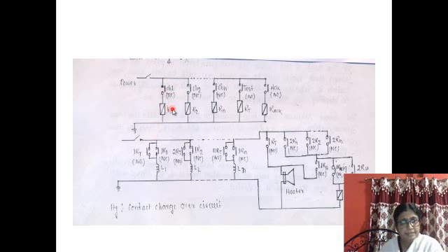As R1 is in energized state, this contact, again, is NC type. As this is normally closed type, and R1 is in energized state, this will be in open state. Normally closed means that when the relay is in de-energized state, the contact is in closed position. As it is in energized state, it will change position to open.